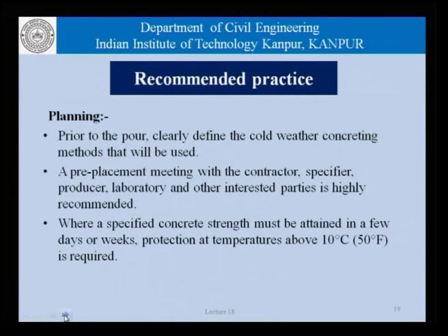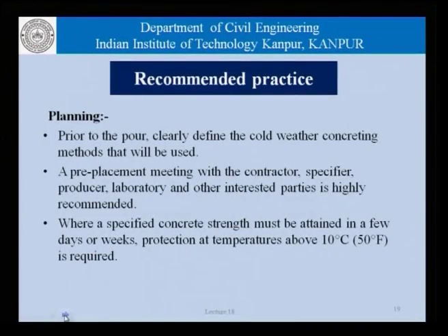This can be ensured through a meeting or a discussion where the contractor, the specifier, the producer, the laboratories involved, and everyone have a clear understanding of what their roles and responsibilities in the operation are. Where specified concrete strength must be attained in a few days or weeks, protection at temperatures above 10 degrees is required.